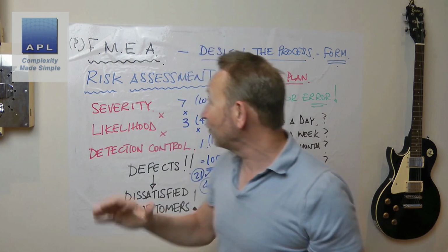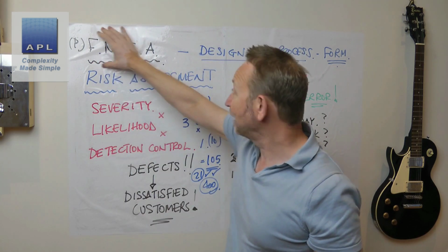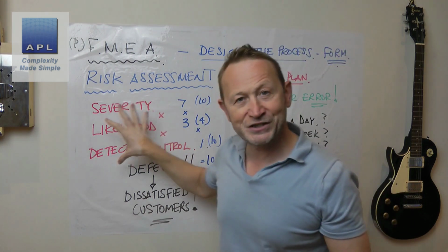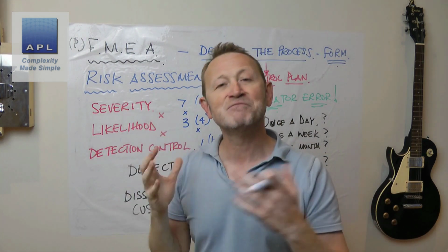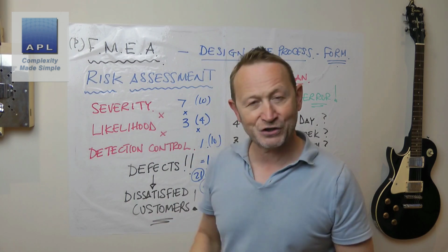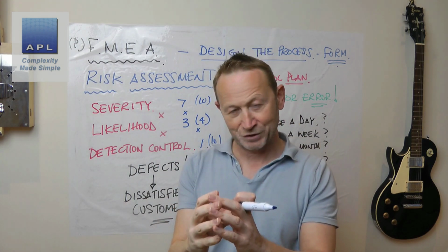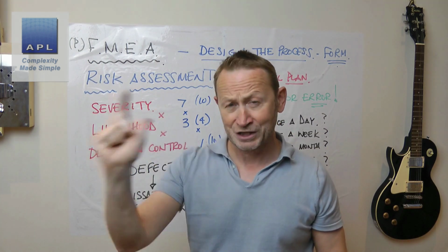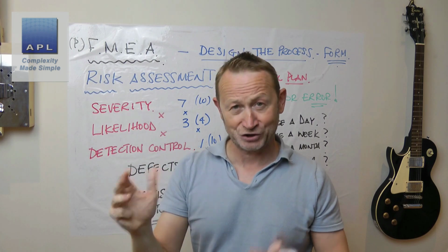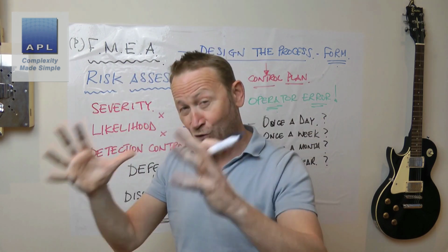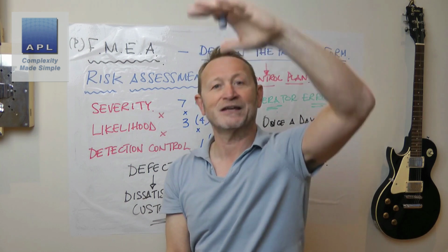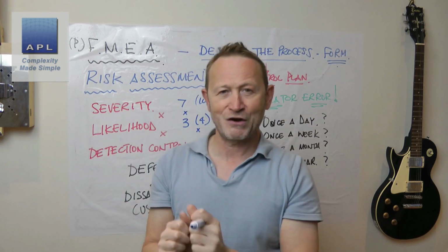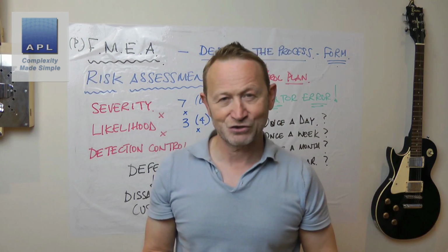So what I've done now, I've told everybody in my FMEA what my process looks like, what my potential risks are in terms of making defects and upsetting the customer. So I've told them how important each variable is in my process: times, temperatures, speeds, injection pressures. All of those numbers will be in my FMEA. And I will say, if they get violated, this is how important they are, and here is how I intend to control them.